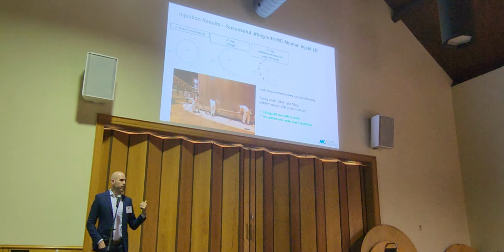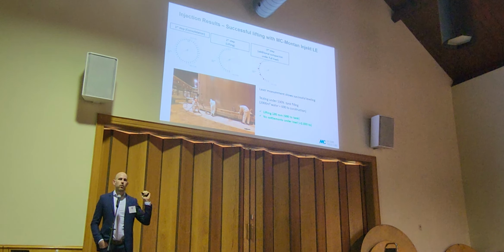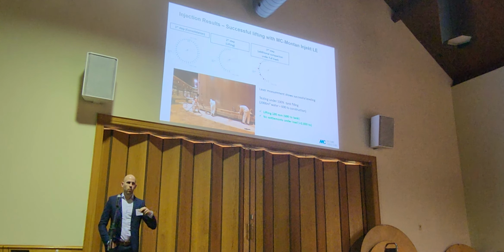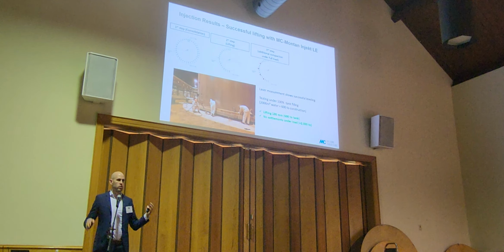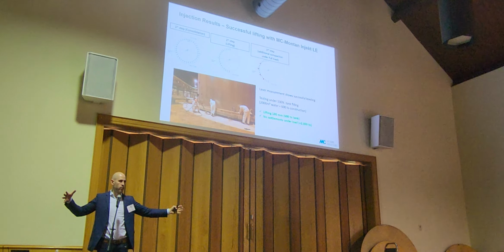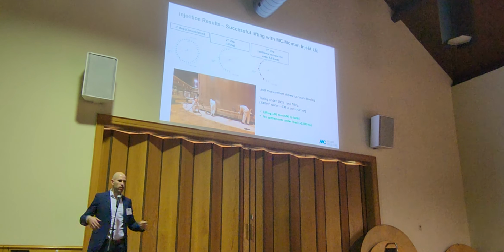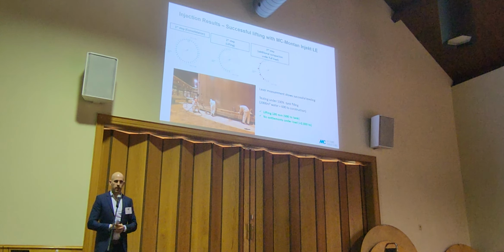If you use different methods, you might use much, much more. Why? Because this resin is expanding with pressure, and we are talking about maybe 10 liters per cubic meter of soil of consumption to reach an area of from 1 point to 1 meter.